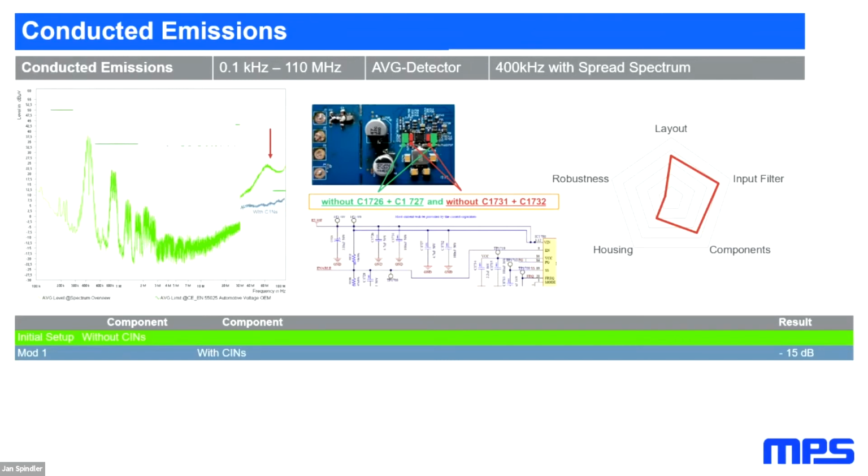Last time we had a board with, I think, more than 20 switching regulators in the application. You see always, when someone is switching, they need a current, they need power, and they get it from where a capacitor is sitting. And if your own capacitor is not big enough and the size is not sufficient, then you create a current flow you cannot handle. So that means always thinking about something like this.